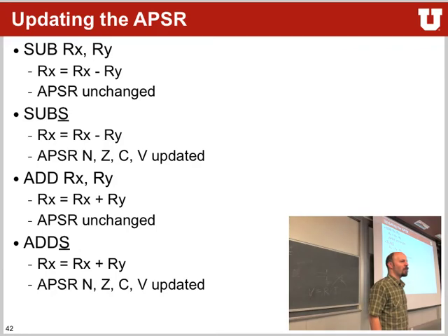Or it gets lost. So that's now either the compiler's or your job as a programmer to say, well, I want to check on the negative result. After this, I want to check, has the result been negative or 0, for example. So you have to use the subs function. But if it never gets checked, you don't have to use the s conditional. And if I'm not mistaken, then the s one is actually a 32-bit instruction, while the sub one is not, if I'm not mistaken. But I have to look at the encoding itself again.